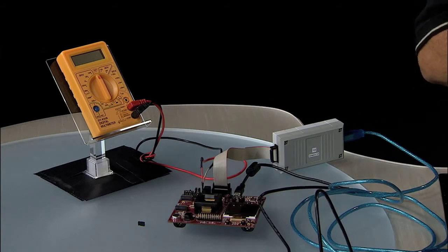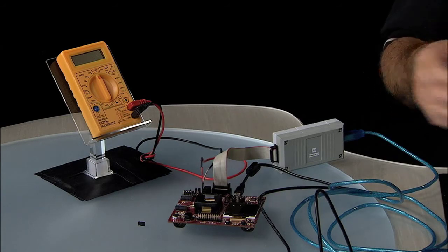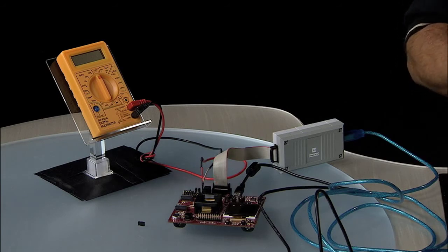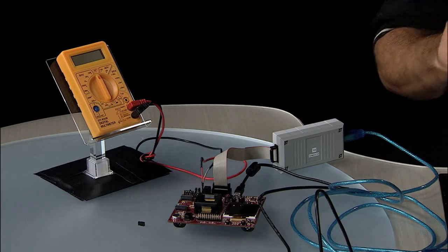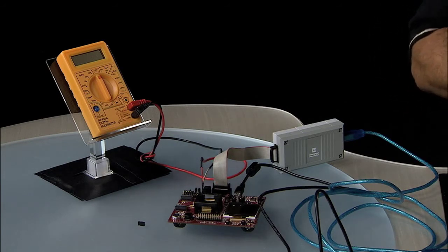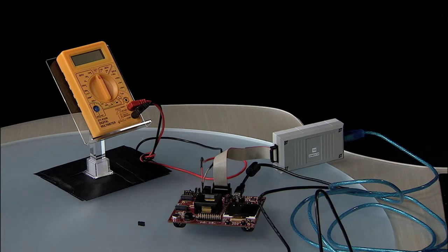The timers are automatically handling the delay time, the trigger time, the settling time, everything that's possible to be saved we're doing in the timers. So although we're not going to see the current drop that much compared to what it did before, this is pretty much as fully optimized as you can get for this kind of application.